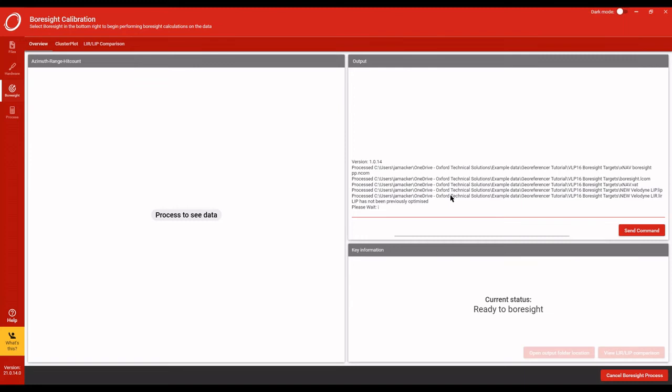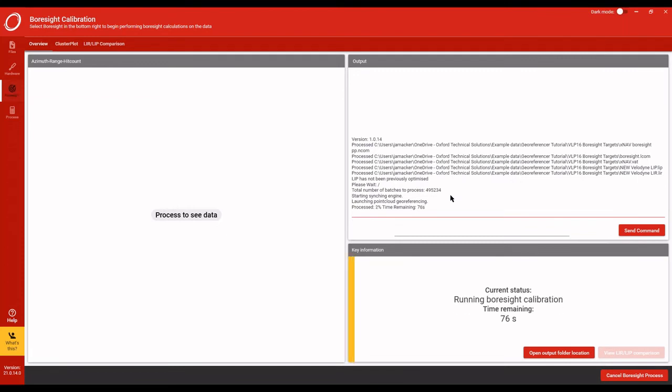What we want to do is have a look at the targets and nothing else in the point cloud. If we can isolate those, we can just look at the targets, and then the software will calibrate the setup by trying to get a best fit of the targets onto what they should be in reality.